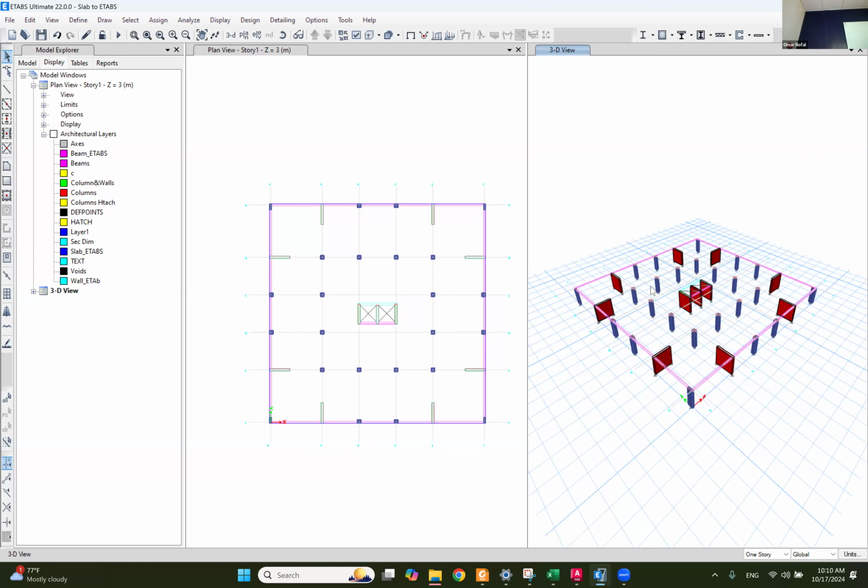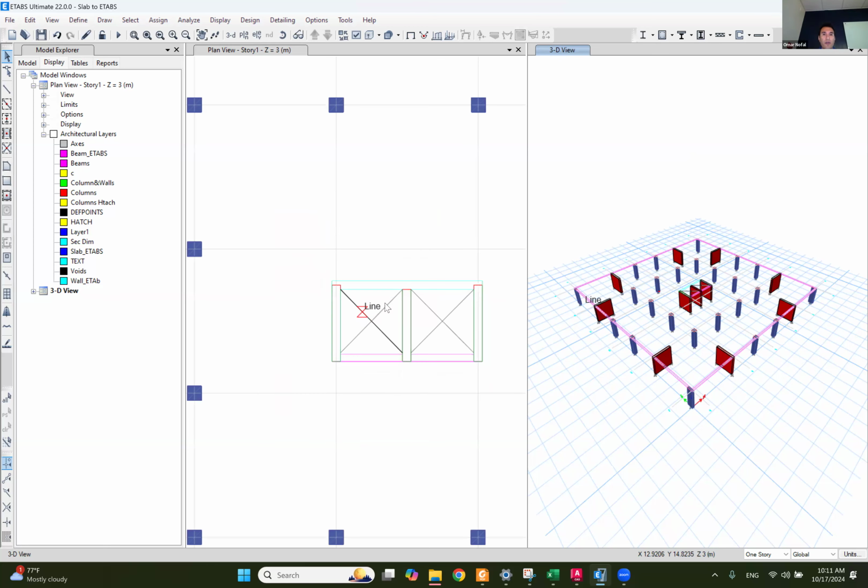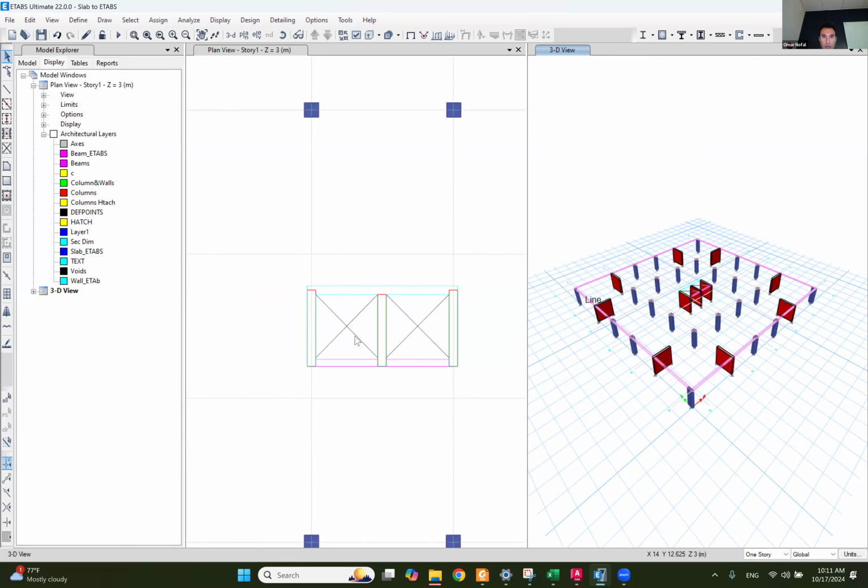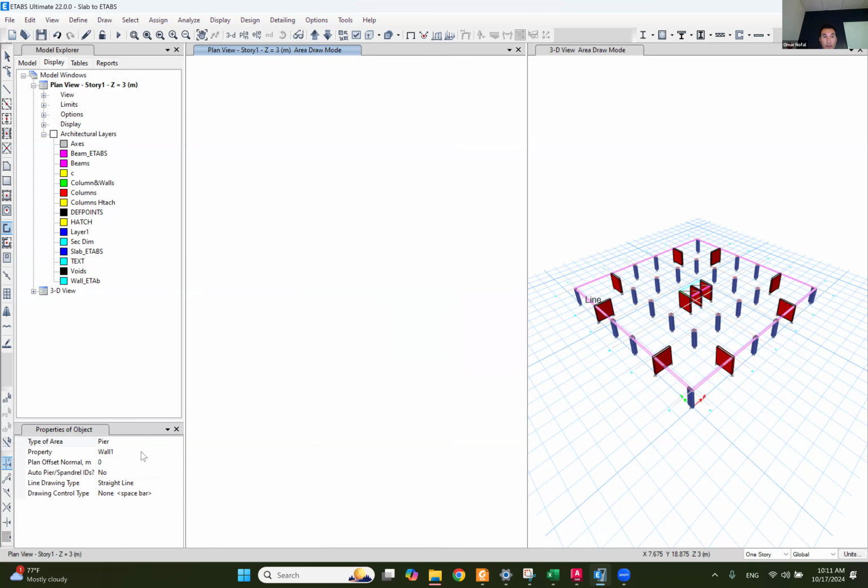We have one problem. I don't know, they draw the entire wall section. So right now we draw 3 walls, but it didn't do this way. I don't know why it didn't do that, but maybe you try it at home. It may work for you. Okay, so if anything didn't work well, it's very easy to adjust. For example, I would come here and this wall hasn't been drawn. So what I'm going to do is go to this option, draw walls, and I'm going to select, I believe this is the wall section that has been used, and I'm going to draw this wall by myself.